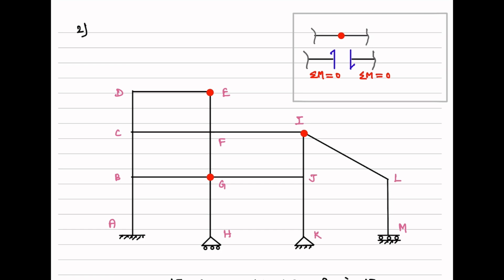However, if an internal hinge is introduced at the same location, the bending moment is released here. So I have indicated only the shear force, but the bending moment is 0. That's why I didn't give this pair.